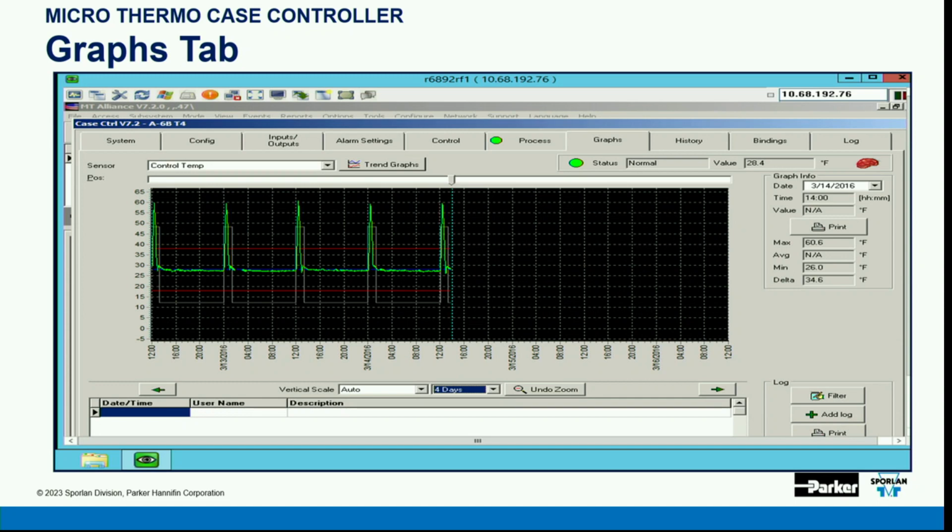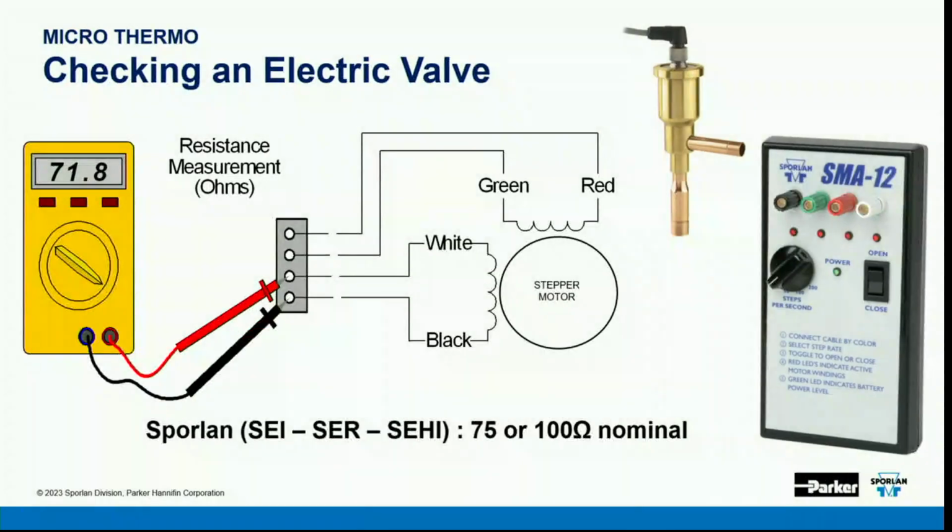Now, take my word for it, you probably can't see. This gray square right here, that's the defrost window. You want to make sure that your defrost is happening inside of that window. If you see this graph is getting lazy and that green line is getting outside of that gray window, you need to go in and correct the pull down to get it down to temperature faster, okay? The bottom line is your customers spend good money to have electronic computer control. Let's just do the due diligence and tweak it, so that's the type of graphs that you'll see, okay?